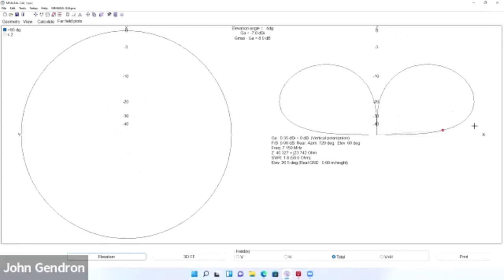So that big bubble of RF, you've got to think of it as a planar front. You're seeing that whole thing move. It hits the atmosphere at different times and drops in different places. That's why sometimes you'll be strong into Texas and strong into California and strong into Hawaii, and then weak into Asia or South Pacific, because of different points where your radiation is going and how many times it refracts and attenuates. Does that all make sense?